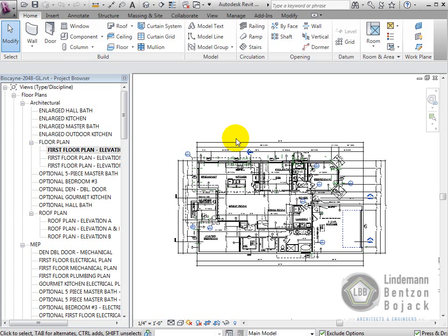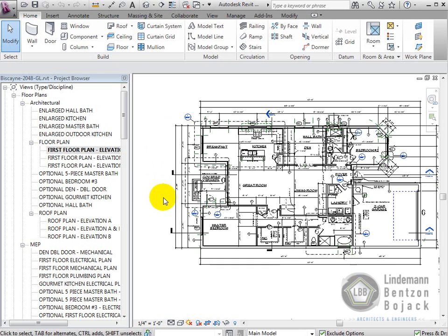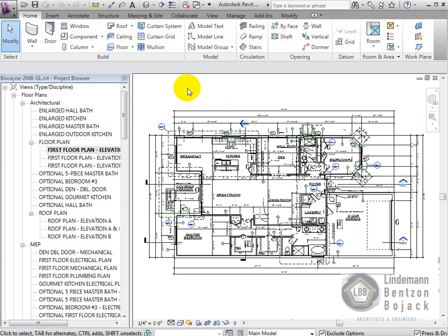In this lesson, we're going to take a look at understanding the garage left version of our Revit models, and just a quick explanation of how they are created. So what I have here is the left-handed model. The right-handed model is linked into a left-handed file and then flipped. What that does for us is it brings over the model and all the annotation, and it keeps it intact. So if we have to change anything, we only have to change it in one location, and that would be the right-hand model. However, there are some exceptions.